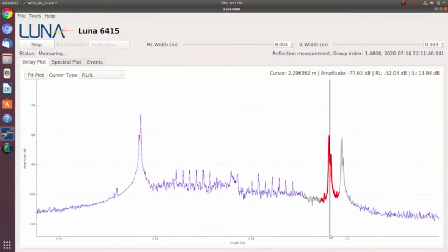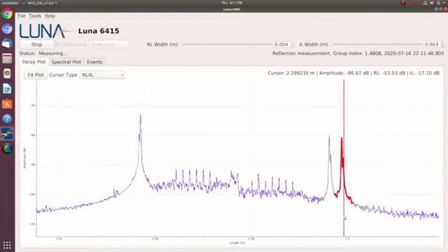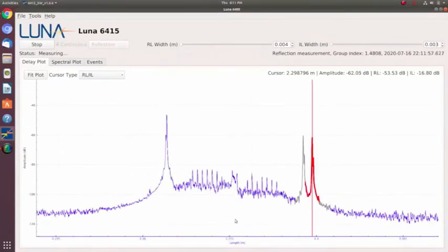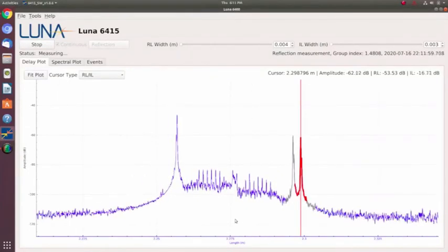There's all the waveguide scatter in the middle there, and then it's 1x2, so the two output paths inside the chip have slightly different lengths. So that's why you're seeing them in slightly different locations. And in between, you're again seeing waveguide crossings where, when the paths cross, you see a little spike with scatter.